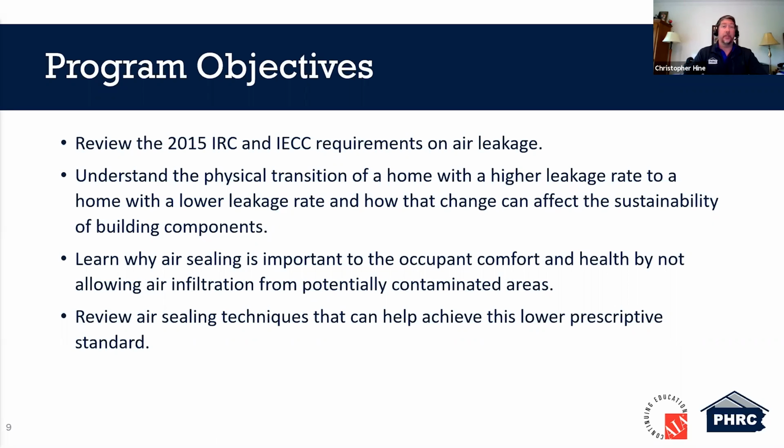We also want to learn why air sealing is important to occupant comfort and health by not allowing air infiltration from potentially contaminated areas, right? So we want to air seal, but we still have to get fresh air into that house. So any air coming in, we want to make sure it's coming from non-contaminated areas. And that's through air infiltration, whether it's through a wall at the garage, that separation, but it also includes exfiltration too, right? So we want to make sure that even the conditioned air inside of the home can be considered contaminated depending on where it might be going.